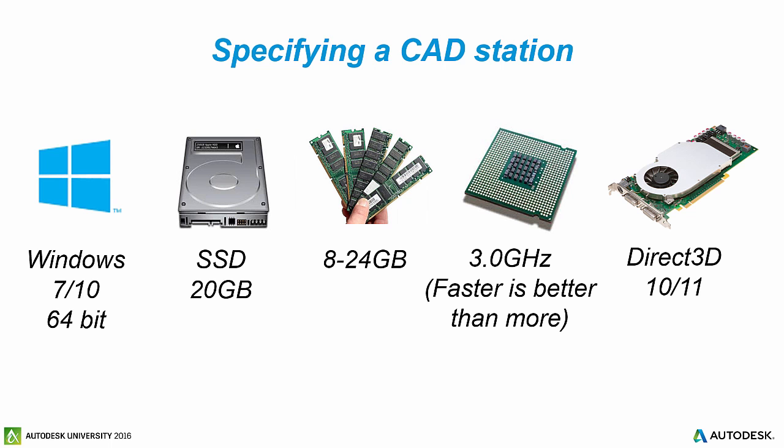I recommend a graphics card running Direct3D 10 or 11. You can check out the recommended graphics cards, the ones that Autodesk recommend, the ones that they've tested. There's a website for that, and I'll give you the link in a moment. You can check out what Autodesk recommend, and also there are recommended drivers. The driver that comes with your graphics card may not be the best driver for your CAD software.